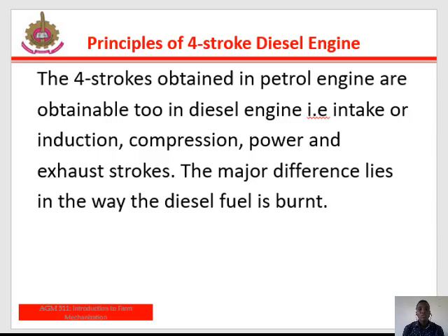Then we have the power stroke. Immediately the compression is ended, an atomized or fine spray of diesel fuel is injected into the already heated compressed air, resulting in spontaneous burning, which pushes the piston downwards. For the power stroke, both the inlet and the exhaust valves remain closed. The direct delivery of diesel fuel into the combustion chamber is accomplished by the injector.